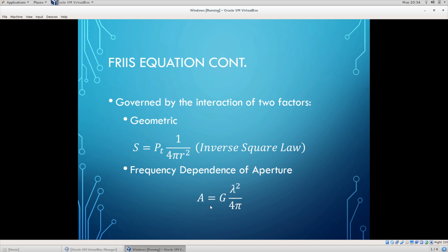That's why in the lab you're going to be asked to integrate over the surface of a patch antenna to get the total average power that you should see in a given location, because it's the surface area over which the energy that is coming towards you is being collected.